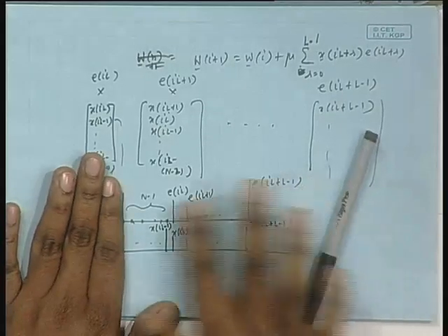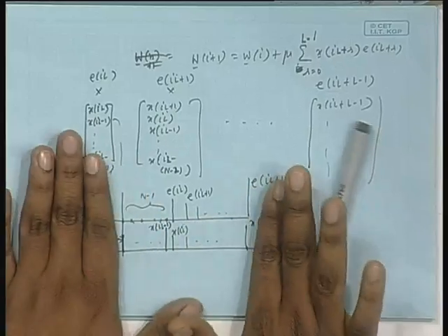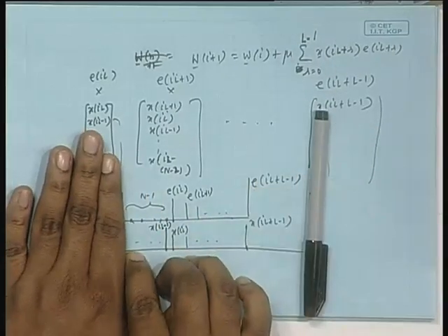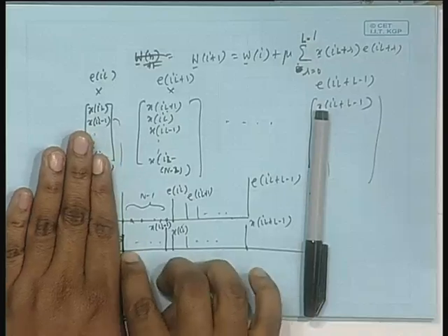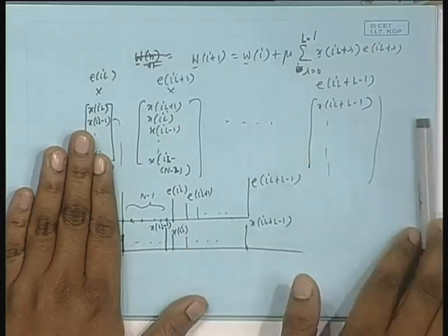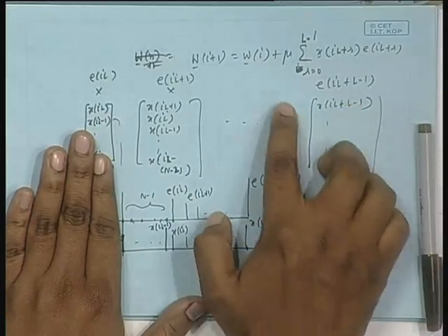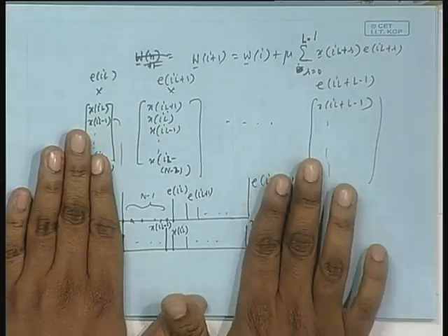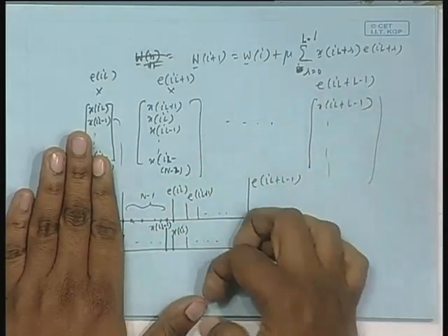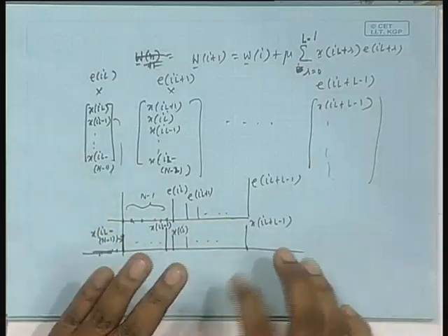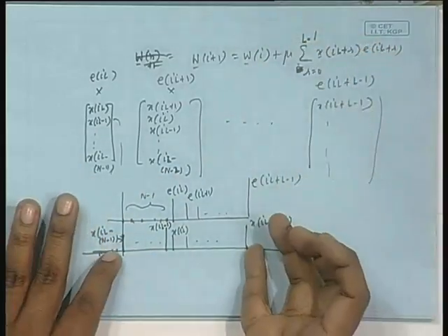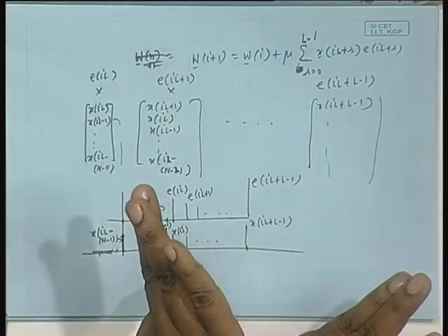First, no shift, multiply, then shift by 1 bit, but chop, confined within this only. From here, if I send in a 0, that 0 comes in, one data goes out, this fellow comes here, this goes out, previous fellow comes here, and again you multiply, add, and go on doing it, isn't it? That is what we do in circular convolution at the later computation stage. So, that means this is obtained by reversing something.